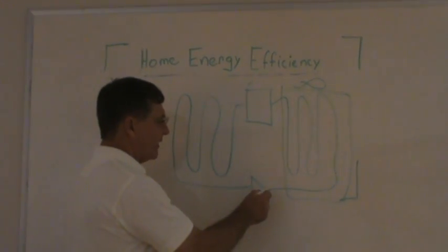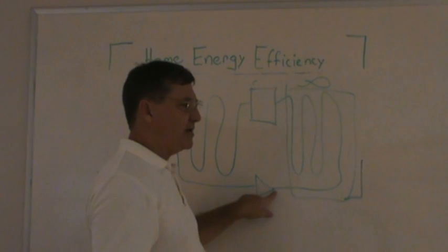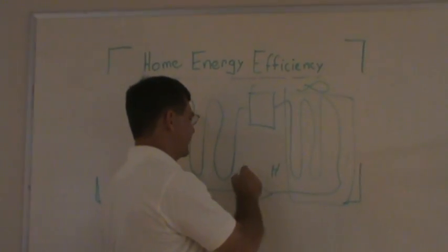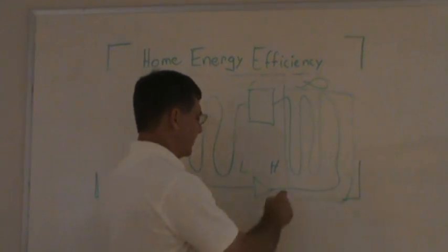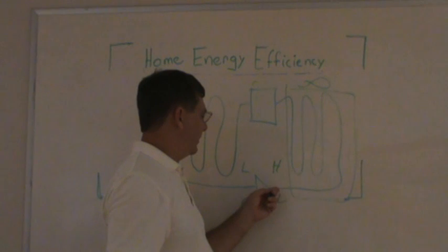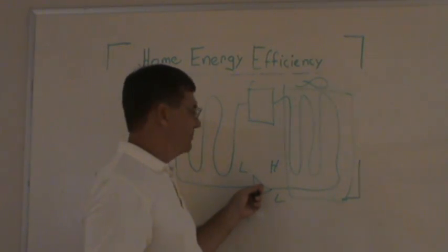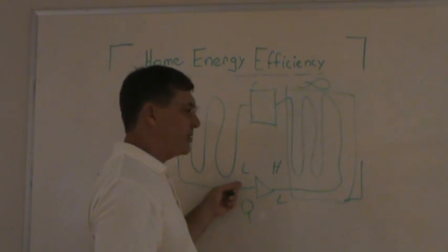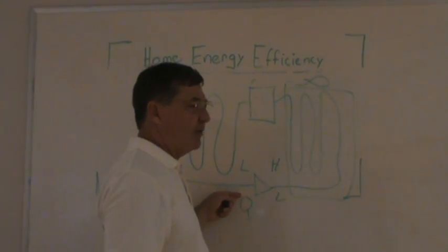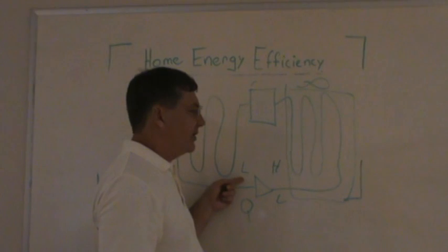So a metering device is a mechanism that allows a pressure difference. Over here, this is a high pressure, this is a low pressure, this is a liquid, and this is a gas. And so the high pressure liquid squirts basically through this metering device. Its pressure changes, and it wants to change state again. It goes from a liquid into a gas.